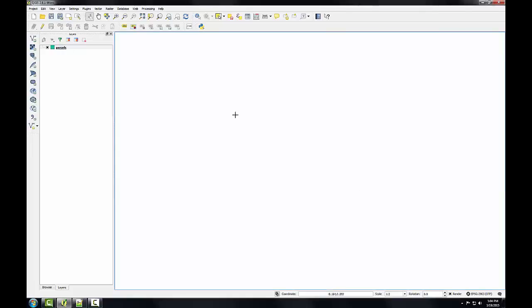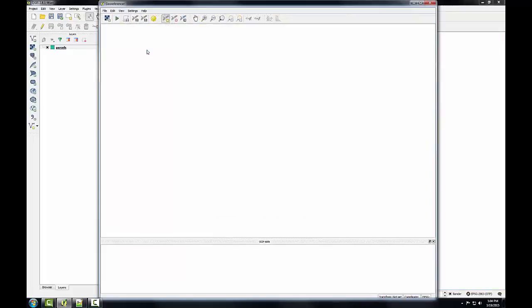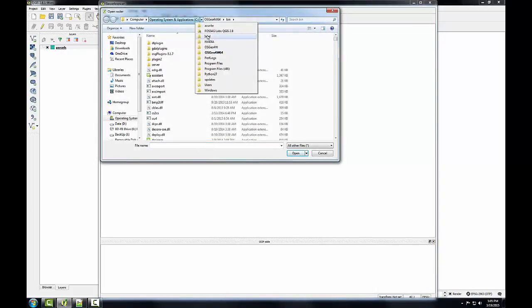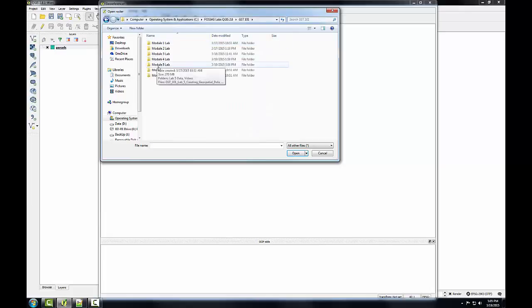To open the Georeferencer plugin, I'm going to go to the Raster menu. I'm going to go down to Georeferencer, Georeferencer. So the Georeferencer window opens, and to get started, I'll click the Open Raster button and add the zonemap.bmp dataset from our sample data. So I'll click this Open Raster button, and I'll navigate to our course exercises, Module 5, Data,